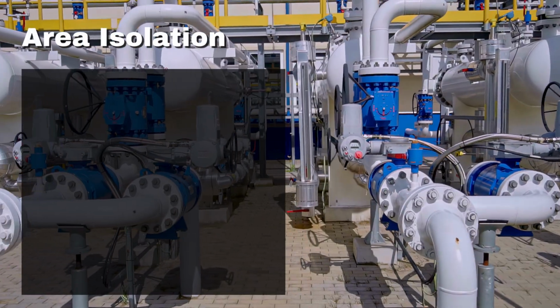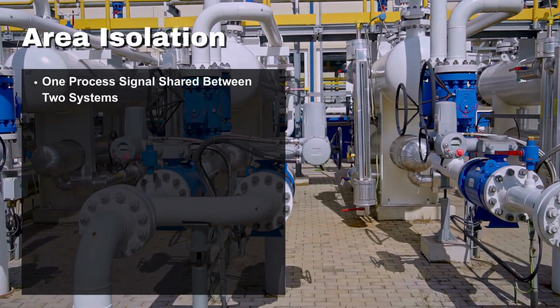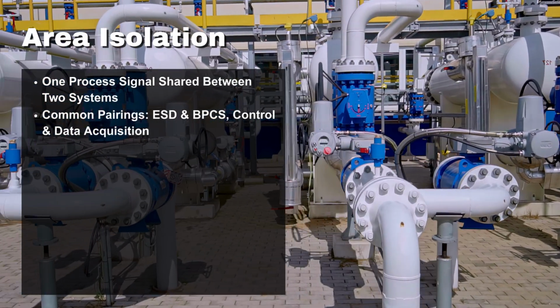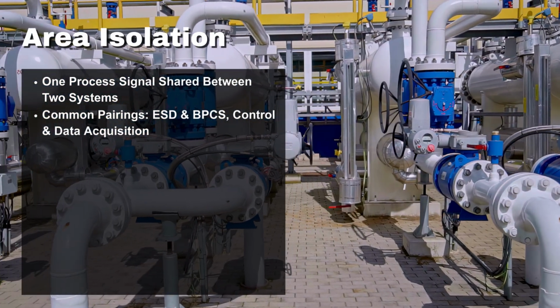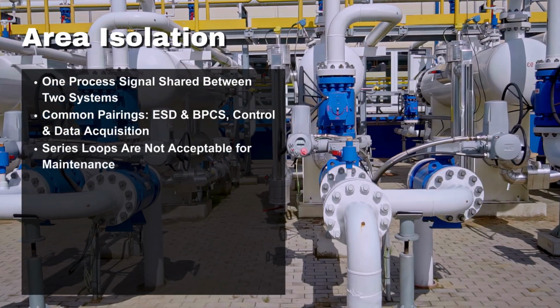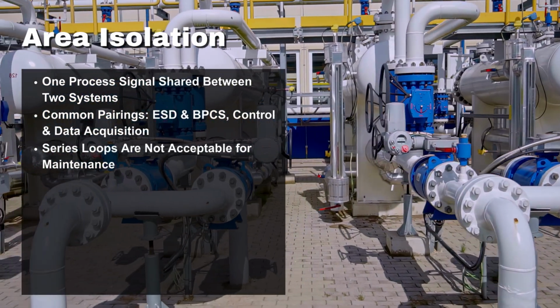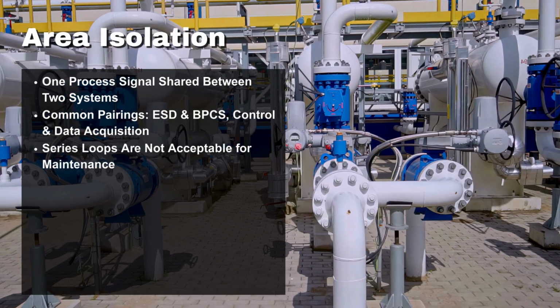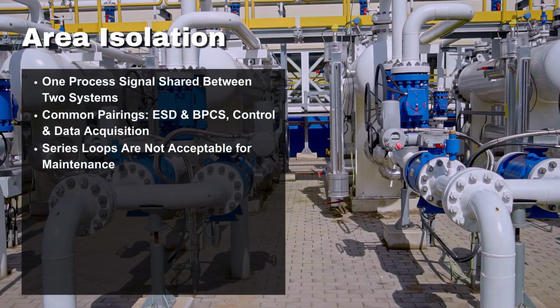In many applications, a single process variable needs to be shared between two systems, such as an emergency shutdown system and a BPCS, or a control system and a data acquisition system. Creating a single series loop between both systems isn't acceptable because disconnecting one input for maintenance would cause both systems to lose the signal.